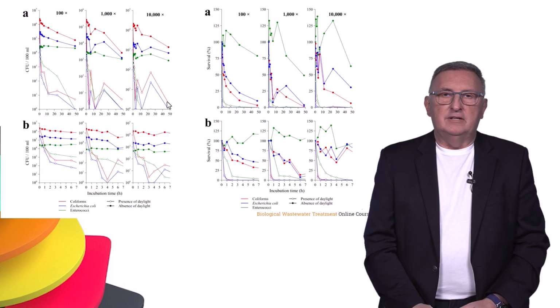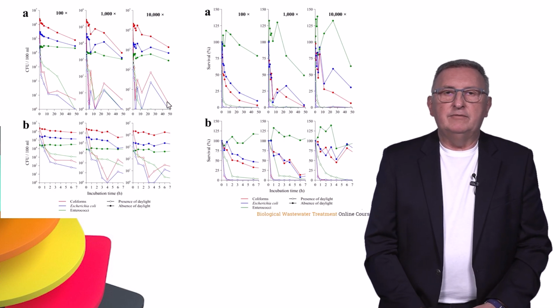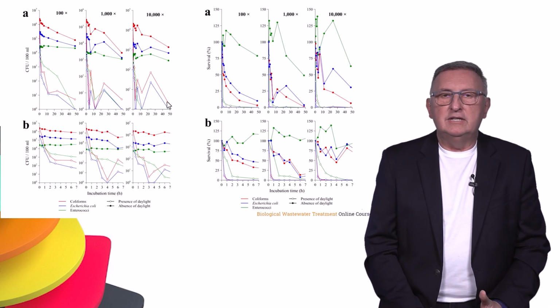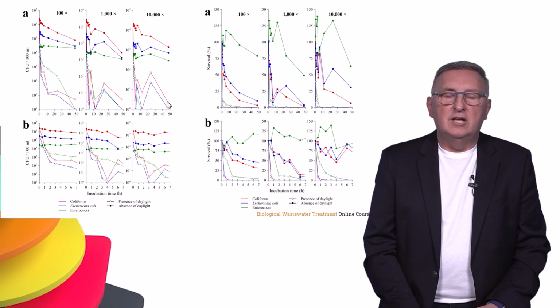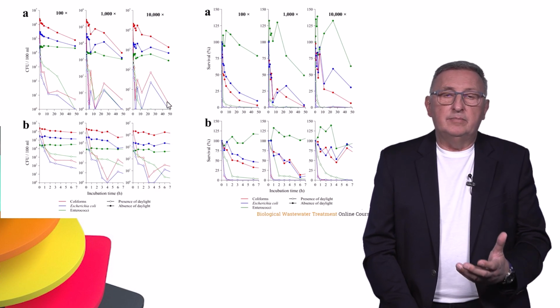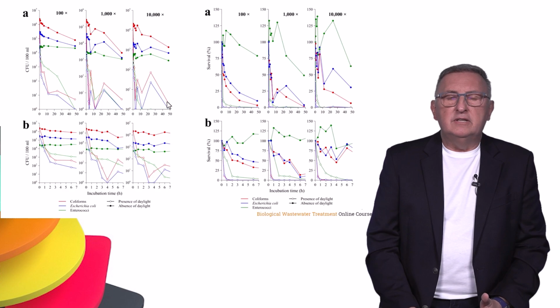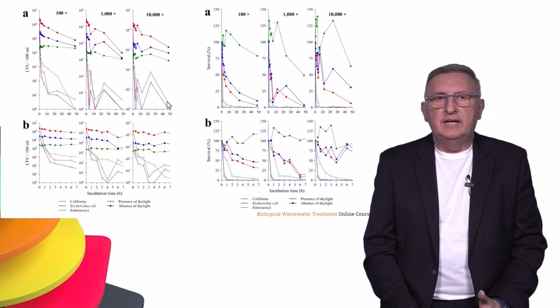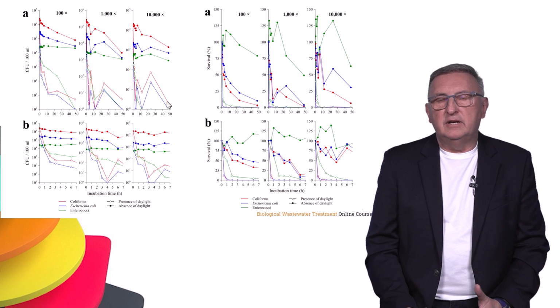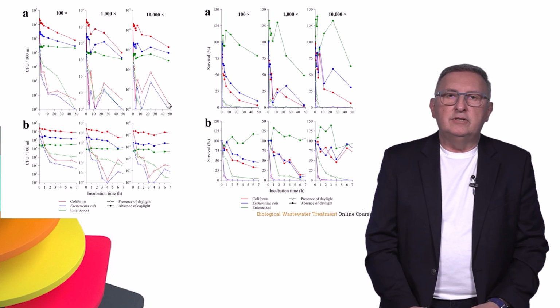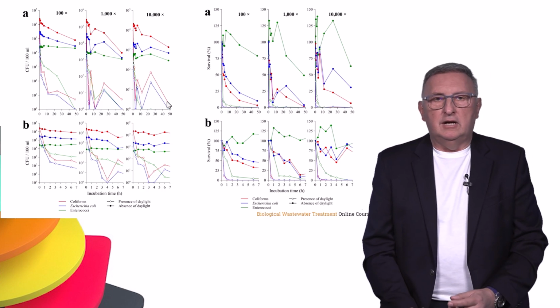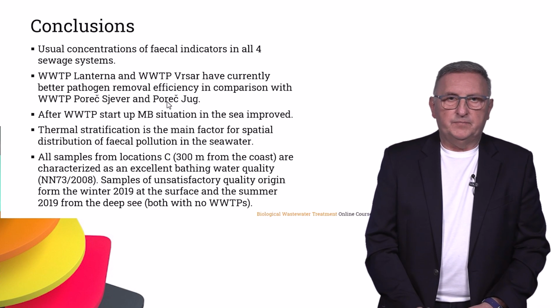On top of that, we also did some scientific research. So we have modeled seawater quality, and I will show you later on a very detailed story about that part of modeling. We also did day and night decay experiments of bacteriological indicators of biological pollution, and we performed a decay test during the night and during the day, and we got decay rates that we later used in a model to substitute the default values in the model so that our predictions are even more accurate.